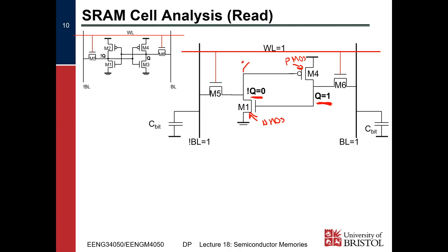Obviously, there is an open circuit just here, and an open circuit just here, so this is the corresponding NMOS and PMOS, but they're turned off, right? So we don't have to worry about them. Going up to VDD and down to ground. Point is, they're open circuits because of the value stored, right? So let's look at what happens when we read.